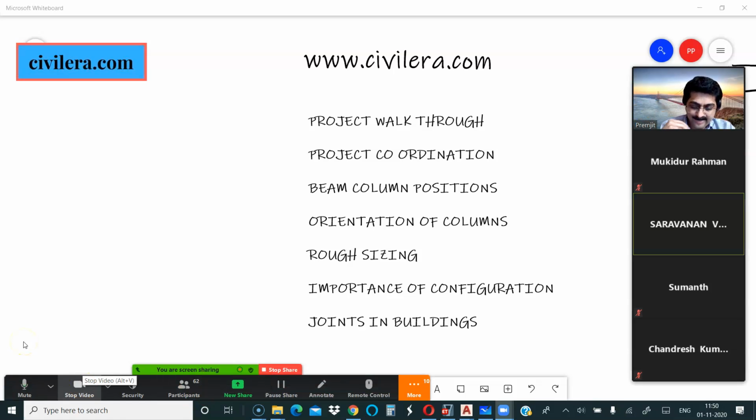Already you told that the 10 floor, 2 floor. Yeah. See, there are various reasons that you may need to have joints. I am concentrating only on the irregularity point of view. There are different kinds of irregularity that you can have in a building. One is your horizontal irregularity, which I spoke about now. When you have an L-shaped or a U-shaped building, then you will have torsion in your building if you don't attend to it. So to avoid torsion coming in your building, I suggested you split that with a joint in between, so that it's two uniform or rectangular shaped buildings.